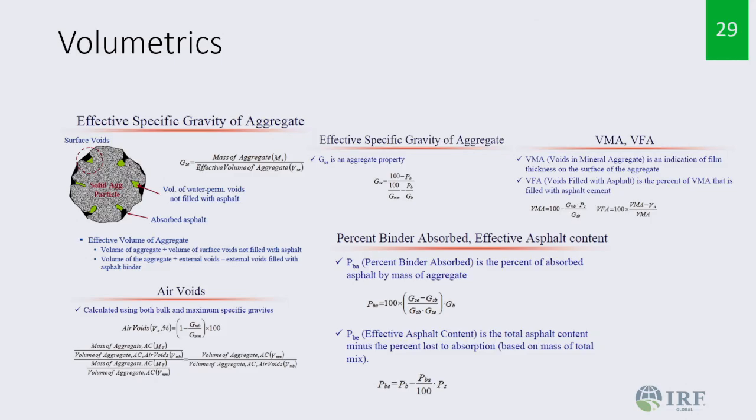So we now will be able to determine the optimal asphalt content that we need to use. What will be the air voids? Because you remember this test, from there we can determine the air voids. What will be the air voids in performance? And then we would normally take some samples and test them. So we'll do a battery of performance tests on the samples that we've taken.